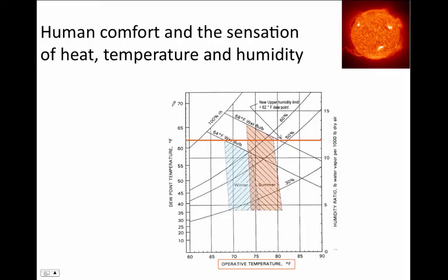So the person could be very comfortable even at a low air temperature. Now, if you take the reverse, they made the surface temperatures of that room like 40 degrees, and they made the air temperature 75, and the person was freezing because even though the air temperature was warm, their body was radiating to all these cold surfaces.